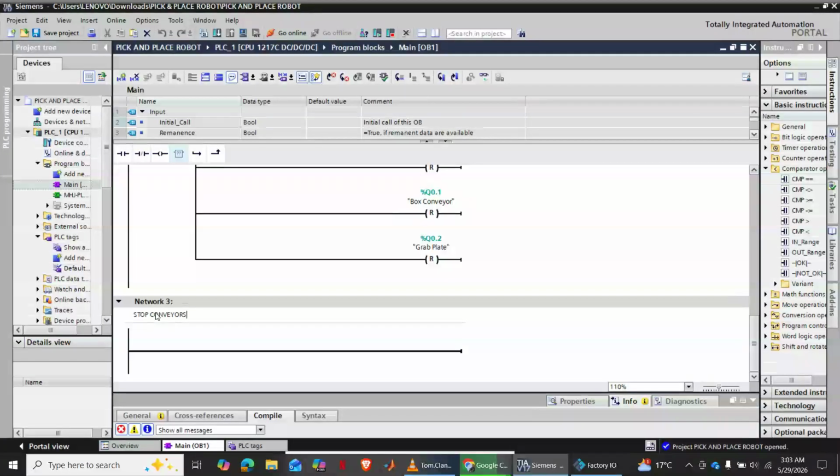But the other thing I should say here, the sensors, I need to have the sensors on the positive trigger. Like if you remember, before we talked about P trig and N trig. So positive trigger is when the box is entering the sensor. So it should activate on the positive going pulse. That way the conveyor stops early, while the box is still at the entry.